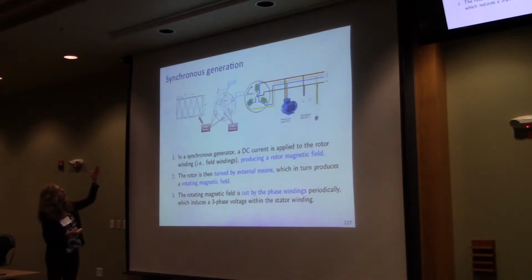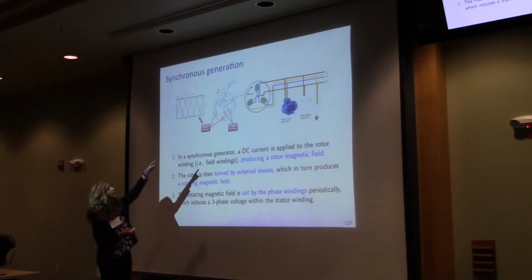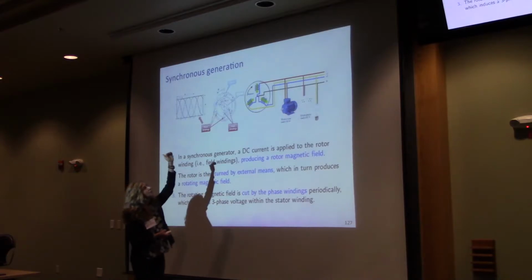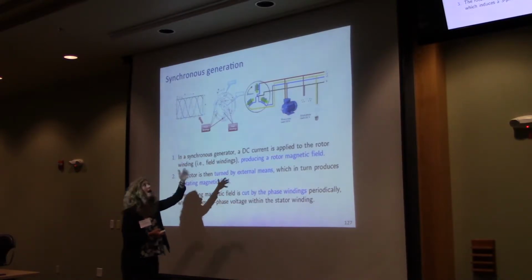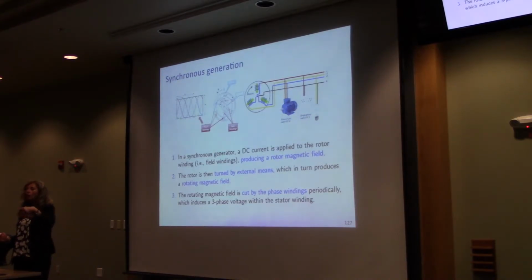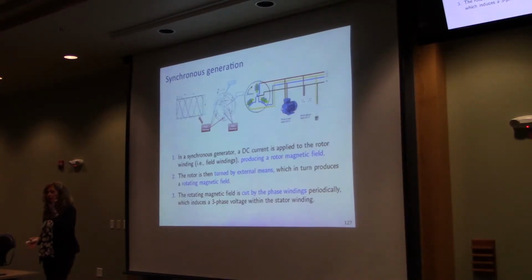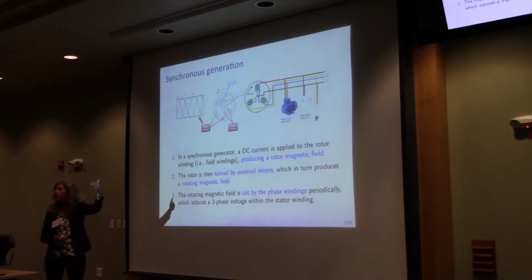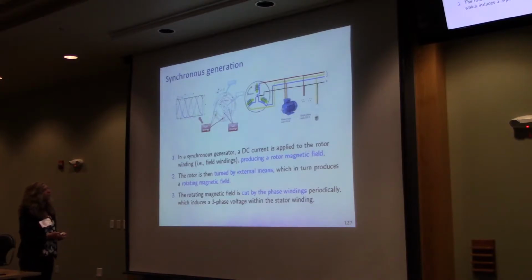And as I said, we produce an alternating current, and typically you produce it on different windings. The normal scheme is that you have 3 wires, and you typically send an exactly equal voltage signal to each of the 3 wires, and that's called balance. This is called the 3-phase circuit. So oftentimes when we describe power systems, we only look at 1 voltage, but in fact there are 3, and they're perfectly balanced. So from one you can reconstruct perfectly the other ones, because these sinusoids are shifted by 120 degrees of phase, right? So you don't really need to describe all the relationships. There is a simplification that takes place.